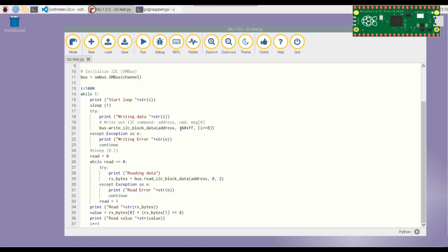However, when I tried that, I wasn't able to get it to work. What happens though is that the Pico can receive both these bytes. If I just put one byte in this list and use that byte as well, then effectively we receive 2 bytes per thing. It doesn't matter whether that's an address or a value. So what it's doing is sending the lower part by masking it with FF just to get the lower 8 bits, and the higher part by shifting it 8 bits.